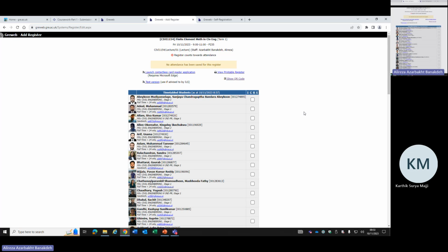The next direction. So we want to create the grid data using edit grids because of the distance. You can have different grids. We had it in one of the examples. If you press edit grid, you can add any sort of grid you like, or you can modify them. They should not always be the same.